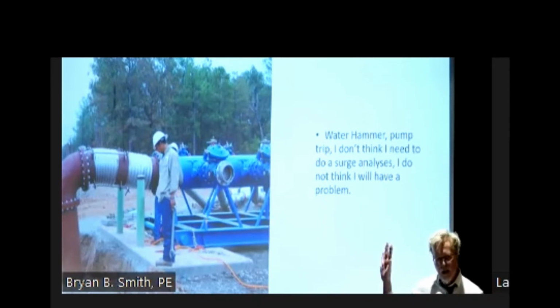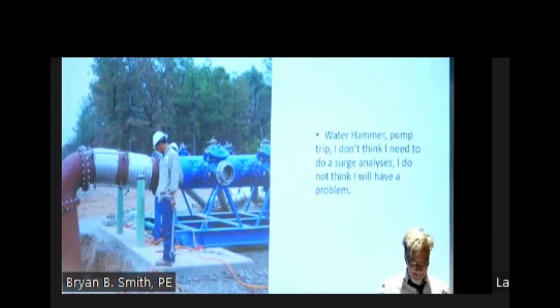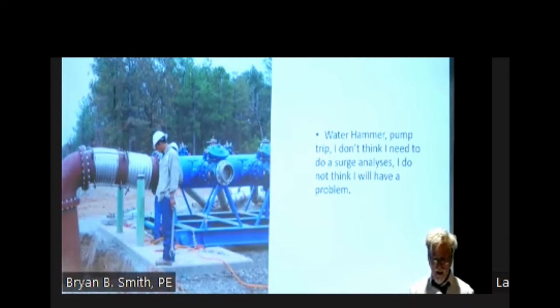I don't know where this was taking place. So this is how you're going to start your pumps. This is how you're going to shut down your pumps. Our system is designed to maintain a constant flow rate and pressure on the suction side of this multi-million-dollar injection pump that's going to bring the pressure up to 8,000 PSI so we can hydrofrack this well.